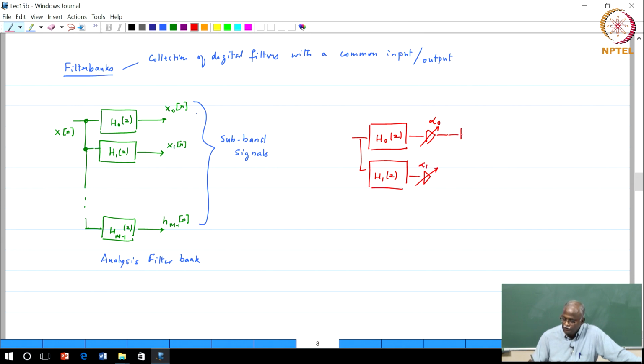This would go out through a small speaker called the tweeter, a slightly larger speaker called the mid range, and the bass usually is the one with the largest dimensions. The high frequency components go through the tweeter, H2(z), which is the one that carries the high frequency.